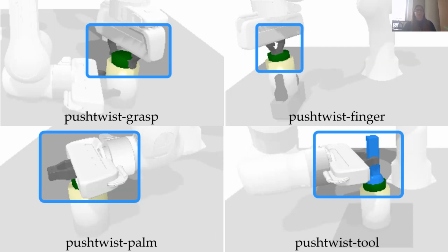And actually, the way we define them, all of our frictional joints are still planar frictional joints. We can use all of our mechanics that we discussed in the first half of the talk. And a precondition for executing any one of these controllers is that the forceful kinematic chain that is constructed is stable. So that is where our forceful kinematic chain check comes in. It comes in as a precondition for executing any one of these actions.